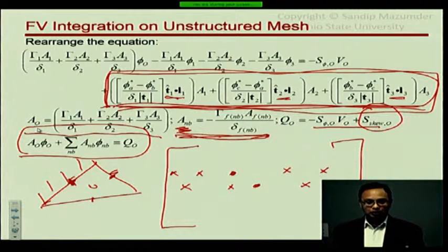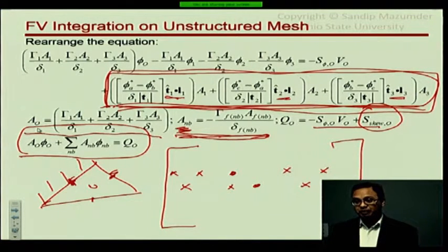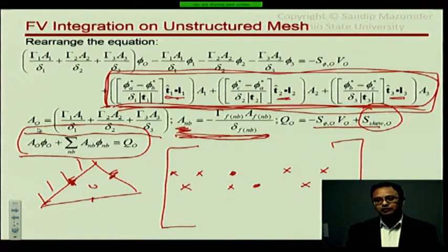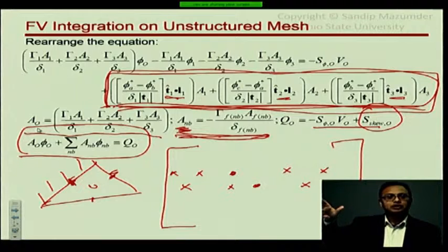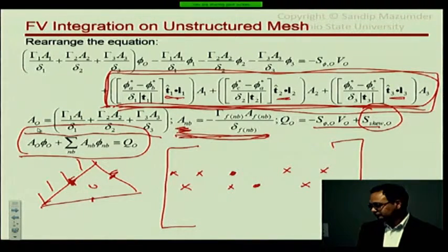Okay, so one of the things that happens now is you can't use solvers like ADI, Stone's, all the ones that rely on the banded structure. You can still use some of the more powerful ones like multigrid. Well, geometric multigrid would be very difficult, but you could still have a structured mesh and treat it like an unstructured mesh and still do geometric multigrid. You can definitely use conjugate gradient, and of course Gauss-Seidel and all the point solvers. So that's the idea.